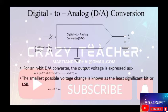The important modules in this process: one is the digital to analog converter, or DAC. The digital to analog converter comes in after the digital processing, when we are trying to give some signal to the environment. The environment is analog, so we have to give an analog signal. The n-bit digital value coming as input to this converter produces a voltage level. If VFS is the full scale voltage, the values range from 0 to VFS.